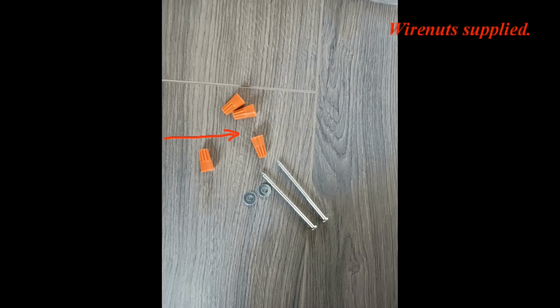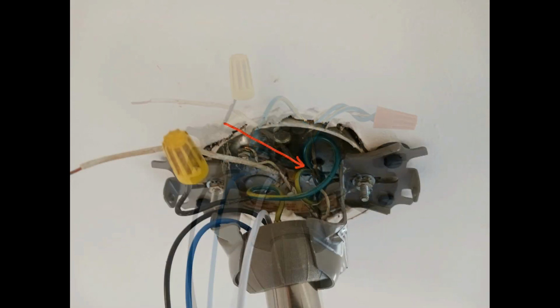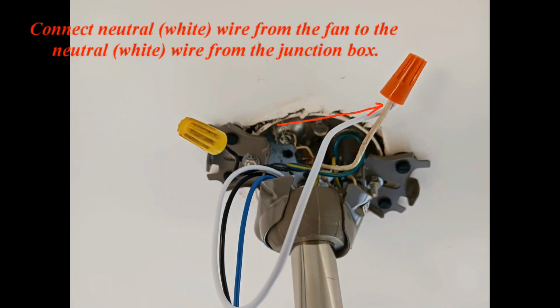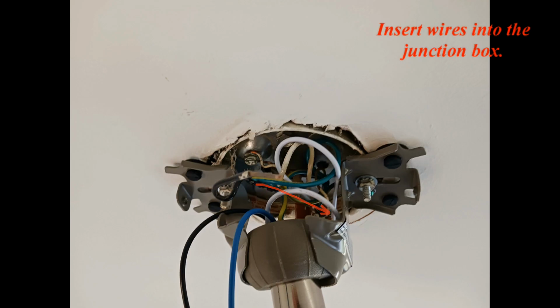Wire nuts supplied. Connect ground wires, green with yellow stripe, from downrod and bracket to the ground, bare wire from the junction box. Insert connected wires into the junction box. Connect neutral, white wire from the fan to the neutral, white wire from the junction box. Insert wires into the junction box.